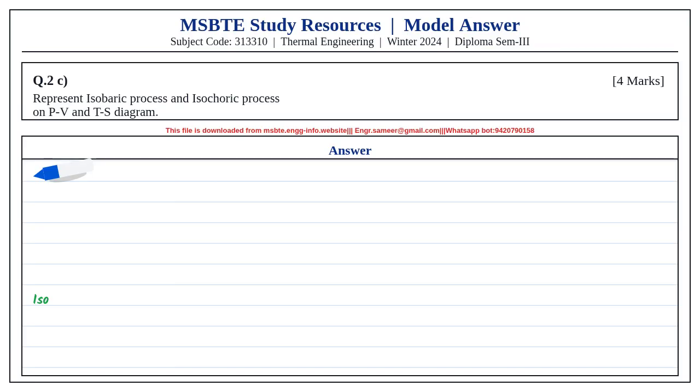For superheated steam, V is equal to RT by P. Therefore, T is equal to PV by R. Substituting values, T is 585 Kelvin or 312 degrees Celsius. Hence, the steam is superheated and the superheated steam temperature is 312 degrees Celsius.